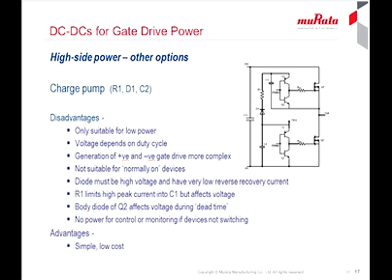Perhaps the biggest problem with this technique is that the high side gate drive power is only there when the power devices are switching. So on startup and during fault conditions, like a load short circuit, the gate is not well controlled and there is no power available for high side fault protection and monitoring. Generally, if the efficiency and fault tolerance of the system is important, the gate drive voltage is critical, and a bootstrap circuit is a poor compromise.